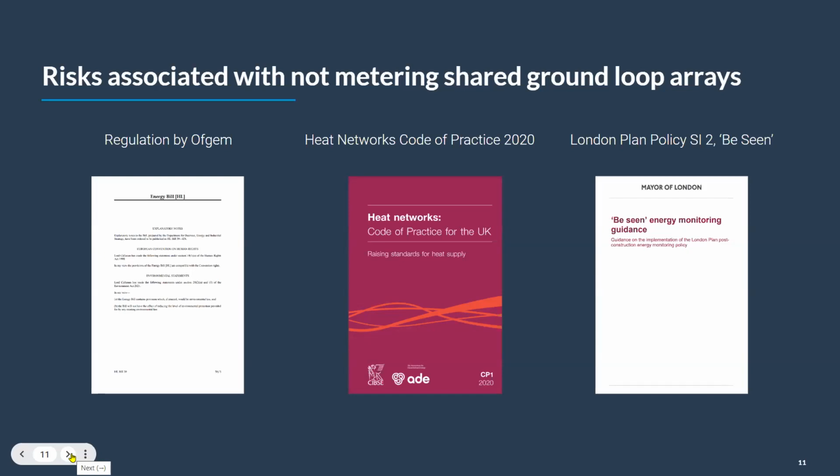And then you've got best practice point, BP 3.8C, which goes a little bit further, obviously because it's a best practice point. It goes further than capturing data every half hour, and states that you should select meters and a meter reading system that are capable of providing meter readings at 5-minute intervals to give residents, customers and the scheme operator even greater granularity, and hence allow more informed analysis decisions about control settings, end quote.